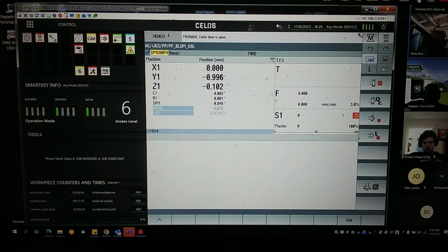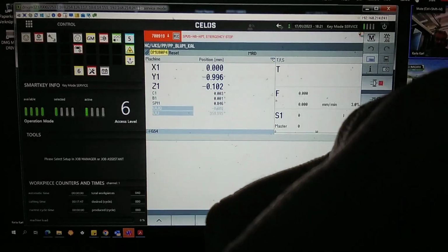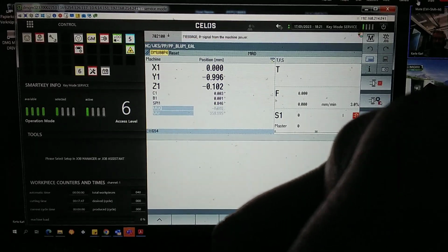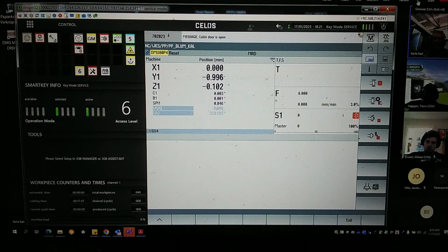Nobody can switch it off. It's not possible. Collision detection happens, as the designation tells you, if you have a crash, and then if you exceed a shock of 20 G for the acceleration, if you have approximately 20 G or you exceed it, then this alarm occurs, and alarm means the machine stops, like an emergency stop. Immediately the axes are powered off and everything is interrupted like that.